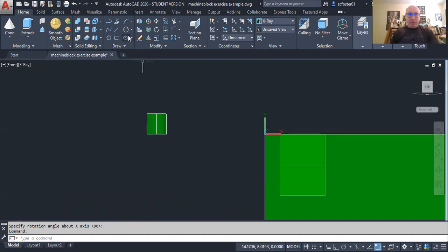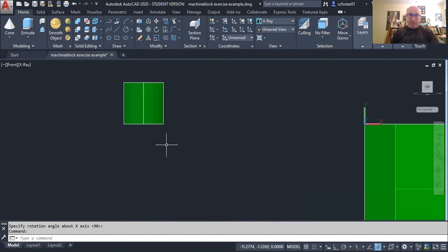So let's start with a polyline command. Actually, let's start with some simple lines. So just a line. I'm going to make sure ortho is on. It's going to draw a line, and I'm going to make it the same distance as the diameter, 2.25. Now I'm going to draw another line straight down from the middle. Don't know how far.